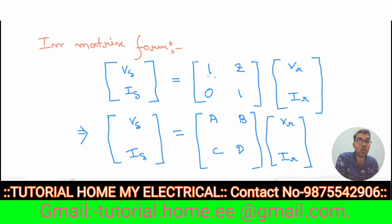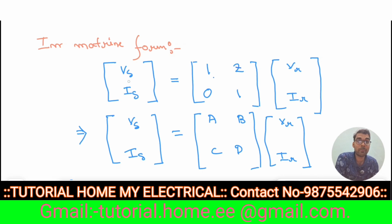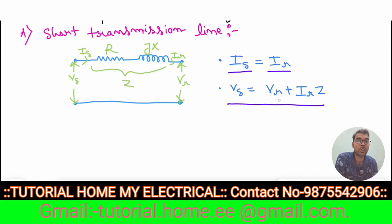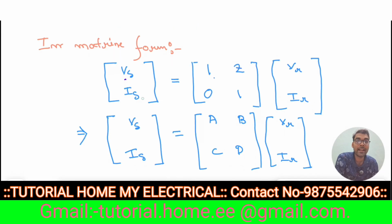Here A equals 1, B equals Z, C equals 0 and D equals 1. From the matrix, Vs equals 1 into Vr plus Z into Ir, so this equation is satisfied: Vs equals Vr plus Ir Z. And Is equals 0 into Vr plus 1 into Ir, so Is equals Ir.